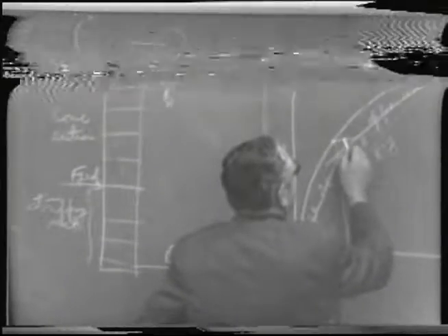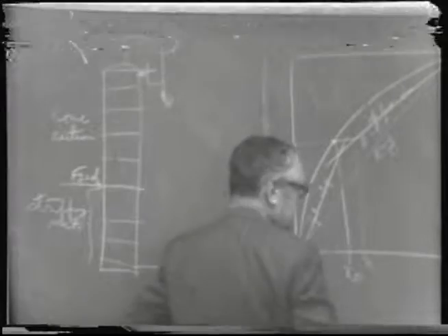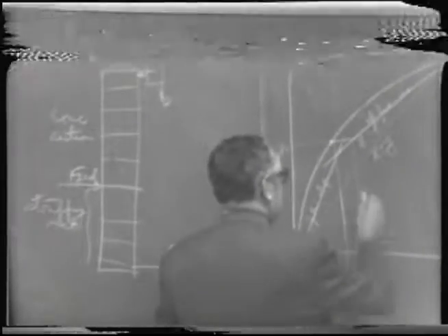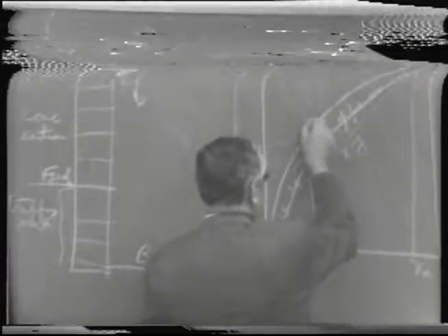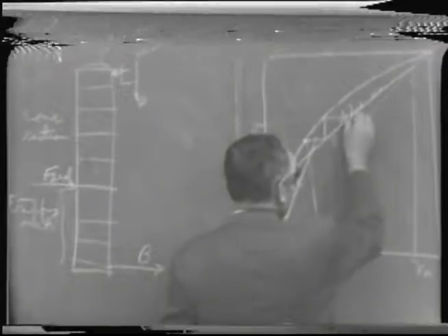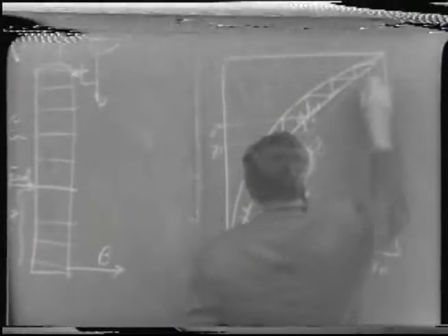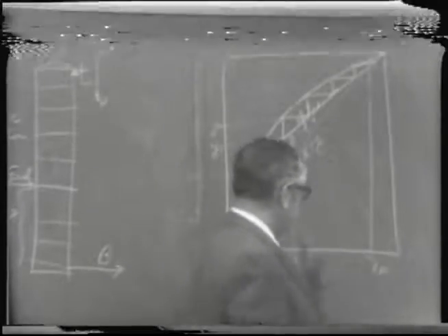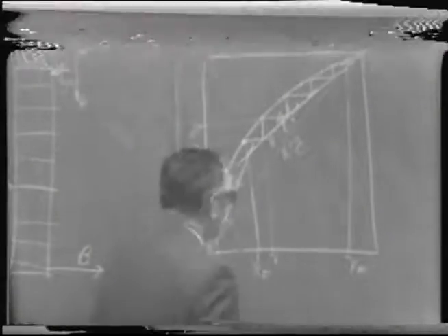When it's condensed, it has a value here of, let's say, X1. This would be Y1, this would be X1. Now then, if it's revaporized again, we get Y2 and we get X2 by condensing it. And so forth, we take our steps here until we have sufficient steps to span the required separation over to a value of X sub P.